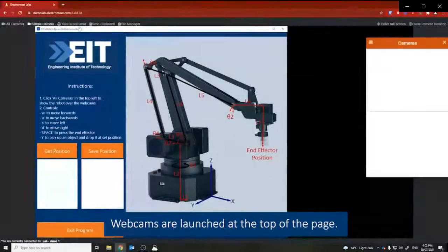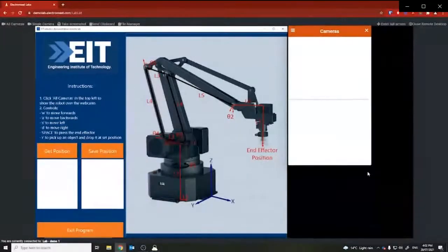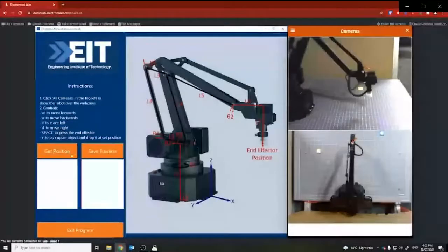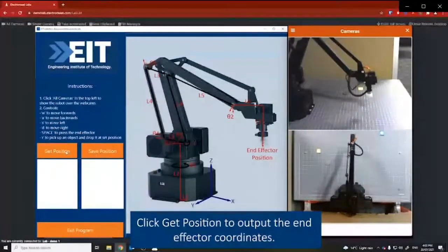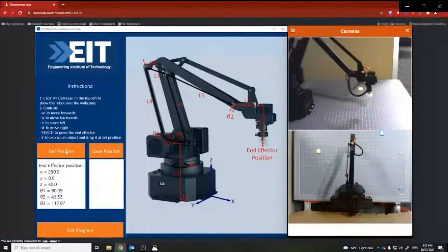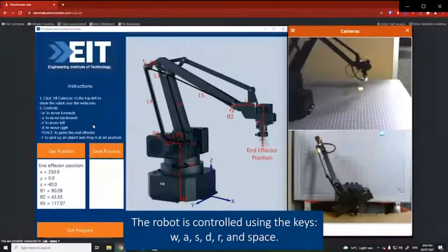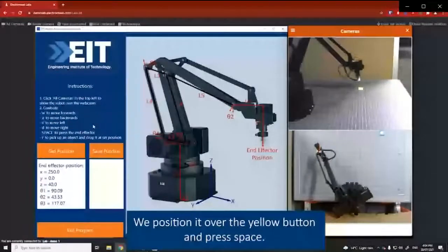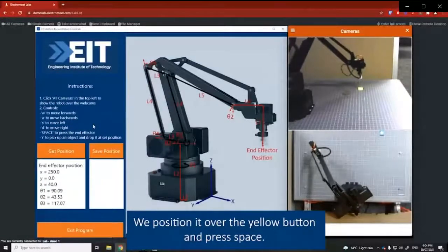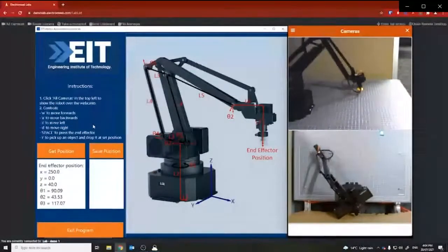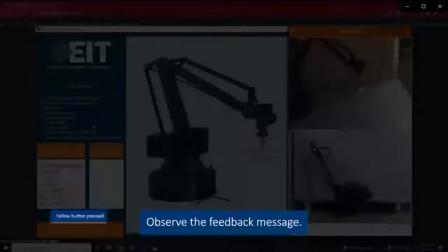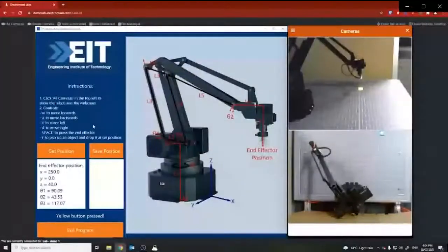It's another little proprietary one. We hooked up a U-arm and controlled it, wrote a little Python script using the Python API in order to give us some live real-time control. This is something we're looking to develop and possibly put into our mechatronics advanced diploma. It gives us real-time control over the robot and lets us output the end effector position.